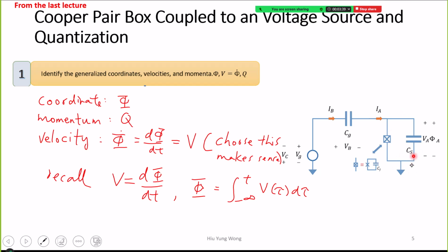And this resembles the LC tank. We have studied the LC tank before, where we have a linear inductor, a geometric inductor, in parallel with the capacitor, and you have a certain resonance frequency. That resonance frequency will determine what type of photon you can store here. And from there, we showed that it will behave just like a mechanical simple harmonic oscillator, right?